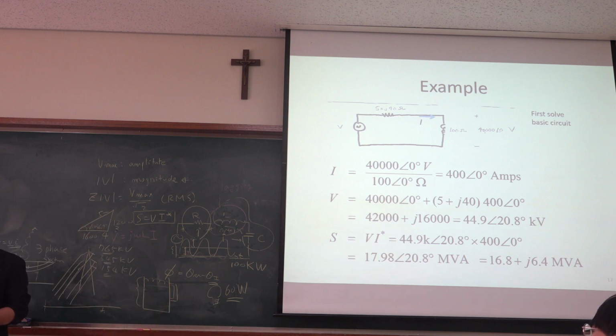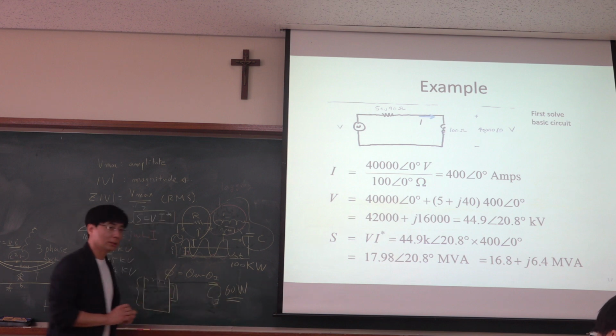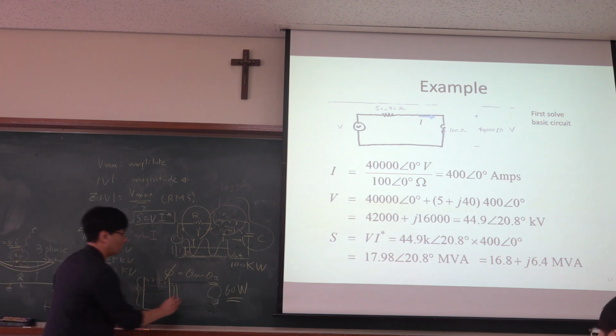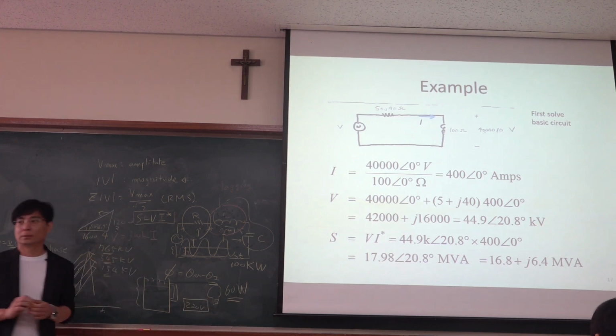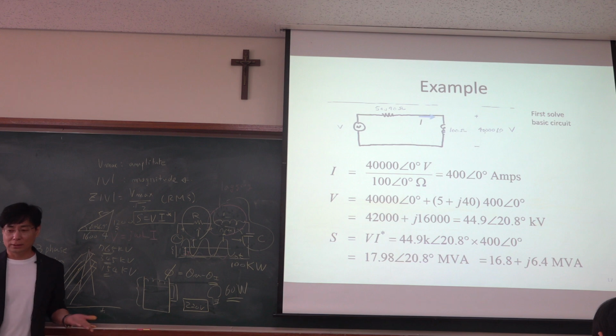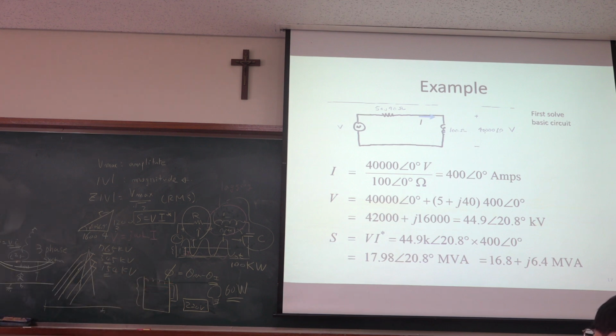In ohm, how much is it? Hey, I gave you all the information. It consumes 60 watt. You know that we are using 220 volt. Then what? 60 watt. What is the resistance? How can you compute that?